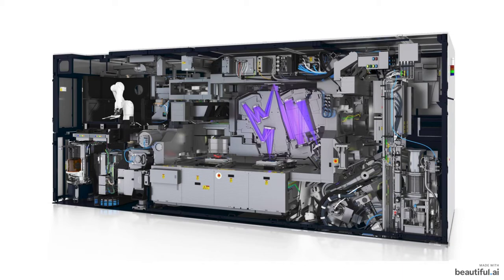So this pattern of light then lets through this print and imprints it on the wafer. So after photolithography, the wafer is then baked and developed, and then the gaps between the different layers in the chip are etched away to give a 3D lattice. This whole process just repeats itself and just creates one layer onto the wafer. So it's repeated 100 times to produce the average chip with 100 layers.